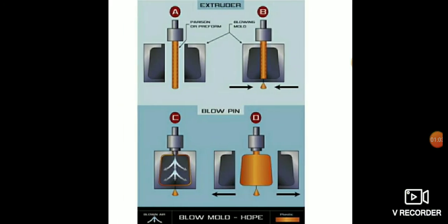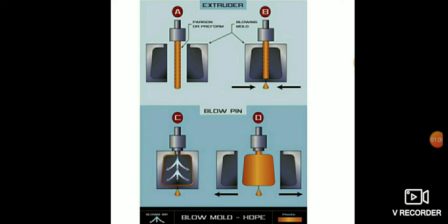Extrusion blow molding is the largest process, and the largest user of high density polyethylene. Blow molding is the forming of a hollow object by inflating or blowing a thermoplastic molten tube called a parison in the shape of the mold cavity. The process consists of extruding or dropping a parison into the female mold, whose walls are then closed.